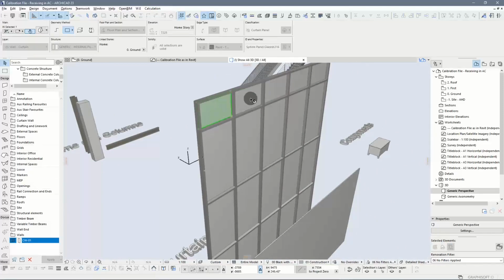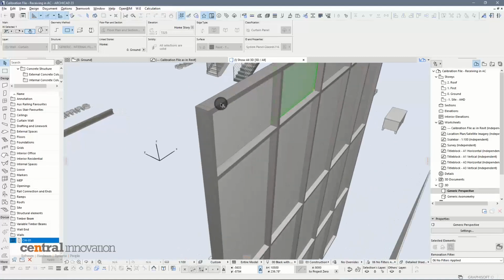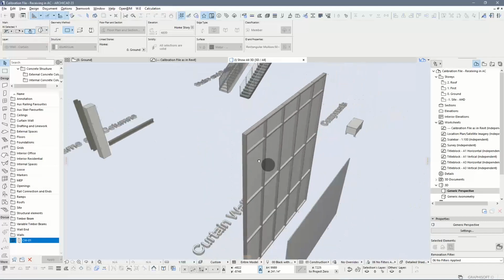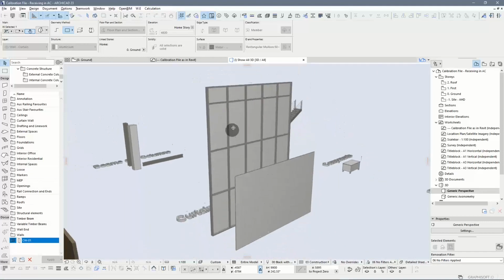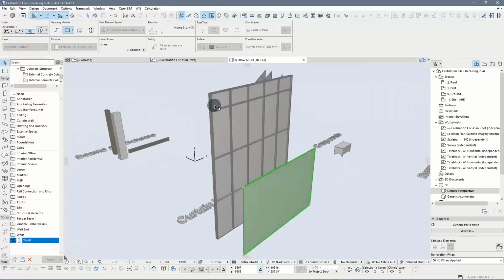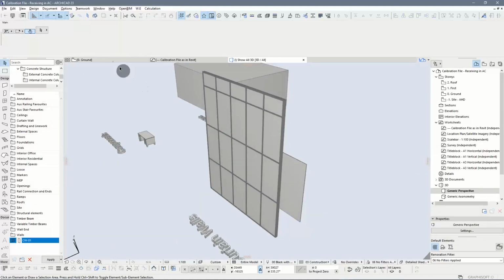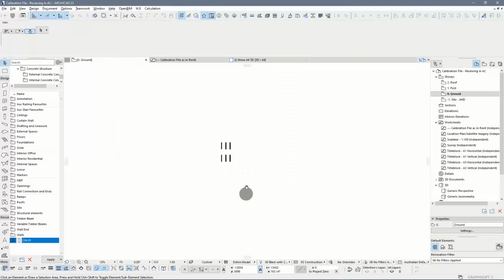Now, this curtain wall, because of the differences in the 2 pieces of software, even though the IFC was an extrusion, Archicad doesn't understand that as to be a proper extrusion, and instead it will build the explicit geometry out of that. So that's based on limitations on every different package. So the case for that will be then, if I cannot reuse it, at least I can measure it.